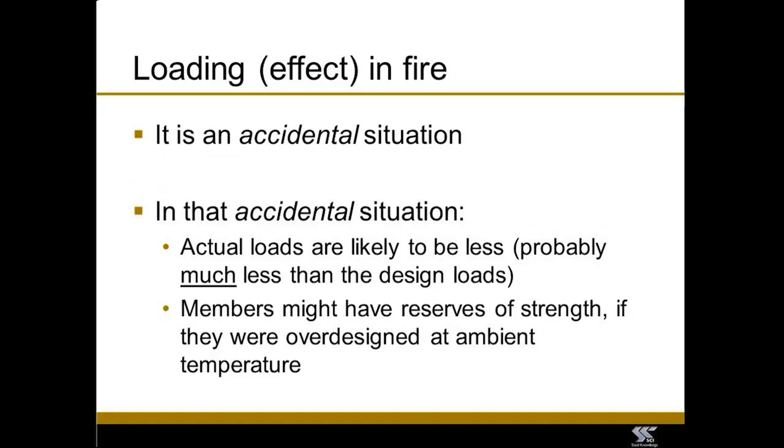So therefore, although we might design an office floor for an imposed floor load of 2.5 kilonewtons a square meter, and then we make that into a design load by multiplying it by 1.5, we must ask ourselves, what is the real load when a fire breaks out? Well, it almost certainly won't be at its full value. It doubly won't be at 2.5 multiplied by 1.5. It won't be at the ultimate value. This is an accidental situation. We just want the structure to not collapse.